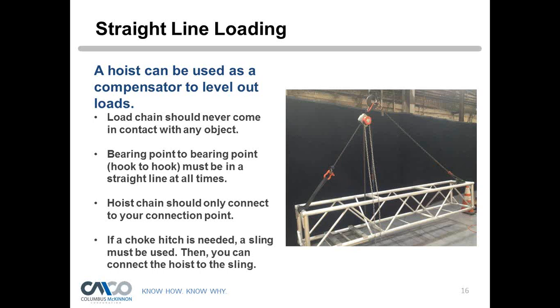And there you can see we've done that, and we've attached our hoist properly where we're not wrapping the hoist chain around the load. We never want to do that. Use the hoist chain and wrap it around and use the hoist as our connection point. That cannot be done.